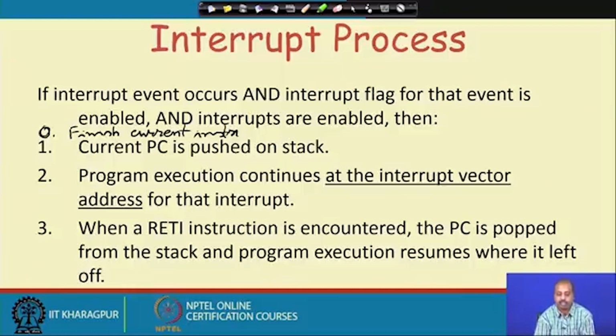So, execution will start at a fixed address, and then after some time when this interrupt service routine is over, the RETI instruction is encountered, and then the program counter is popped out from the stack, and the program execution will resume from the point where it was left off. So, that is the standard interrupt operation flow, and that is true for other processors also. The only thing is that in case of 8051 the interrupts are all vectored interrupts.